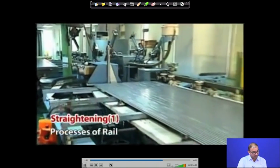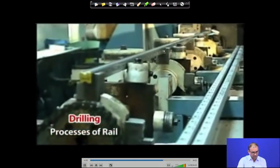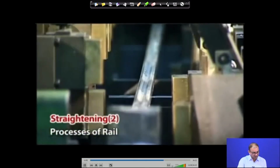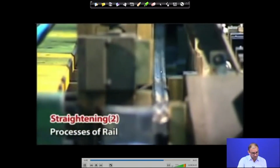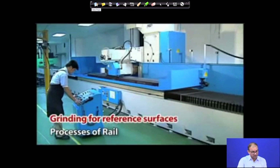So, first you have to straighten it, and then you have to do drilling, because we have to mount many things here. Then straightening process 2: after each and every operation you have to perform the straightening operation again. Then after straightening you have to create a reference surface here. Now, what does it mean?